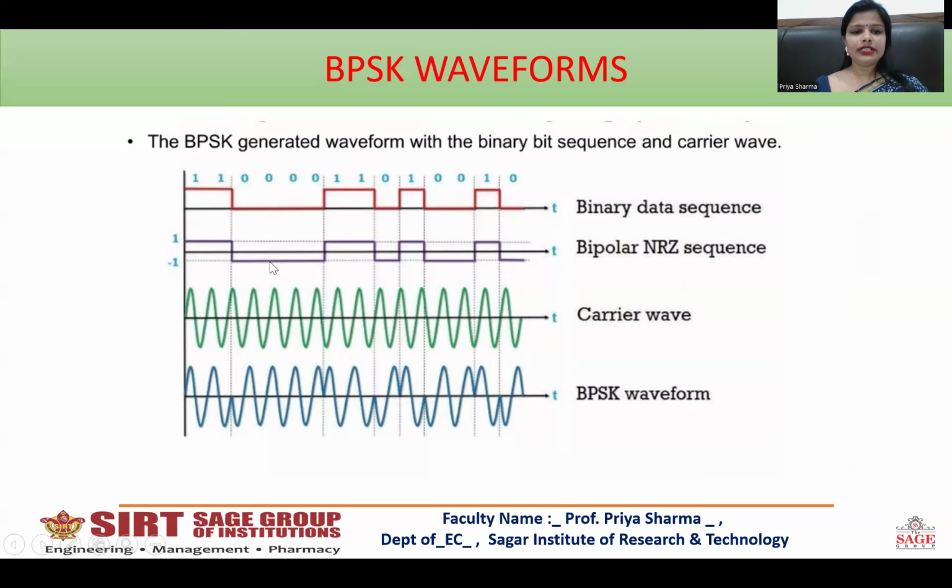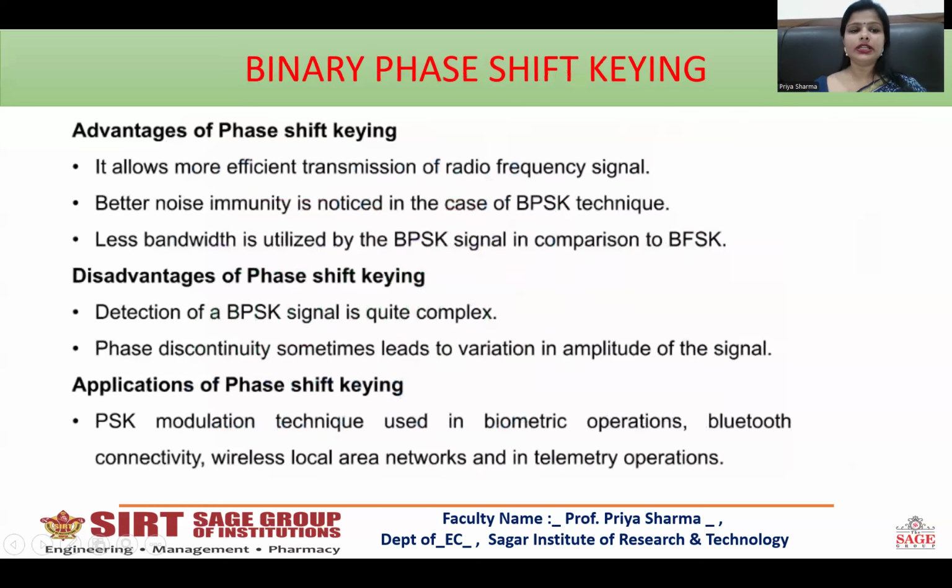And then until the next change in state from 0 to 1, it will follow this phase. As soon as the state changes again, it will have a phase reversal. Then it will follow the same until the next logic change from 1 to 0, and this continues, and this is how a BPSK signal is generated.